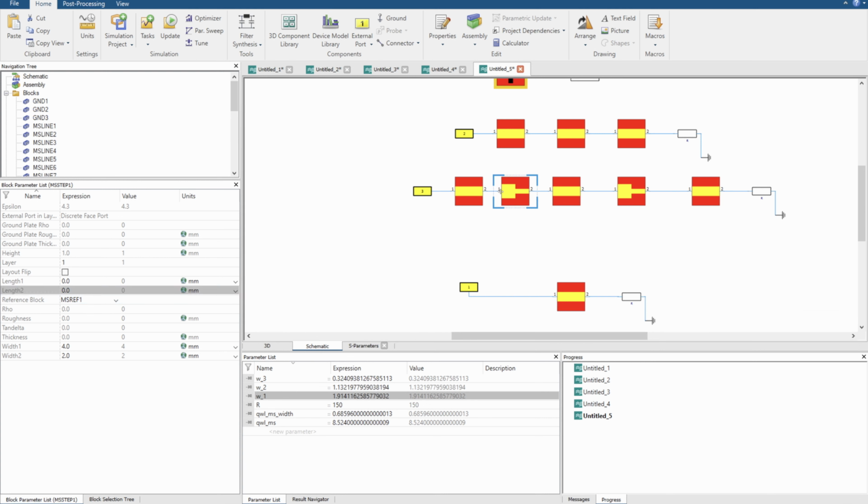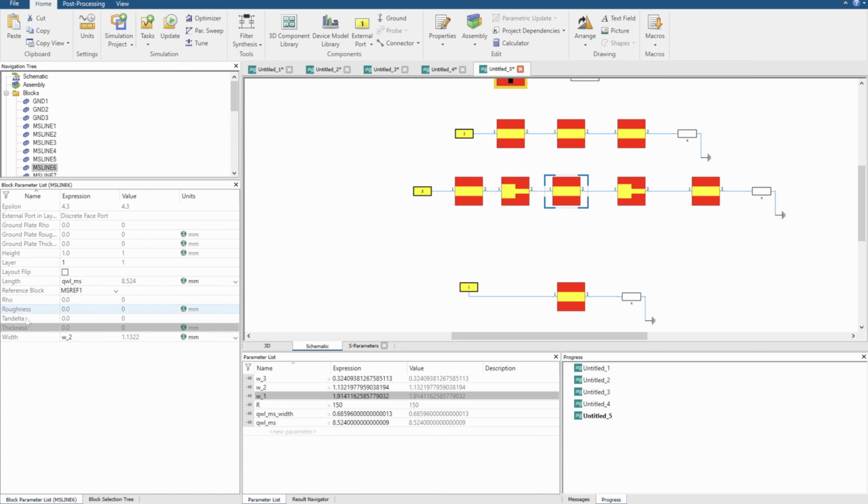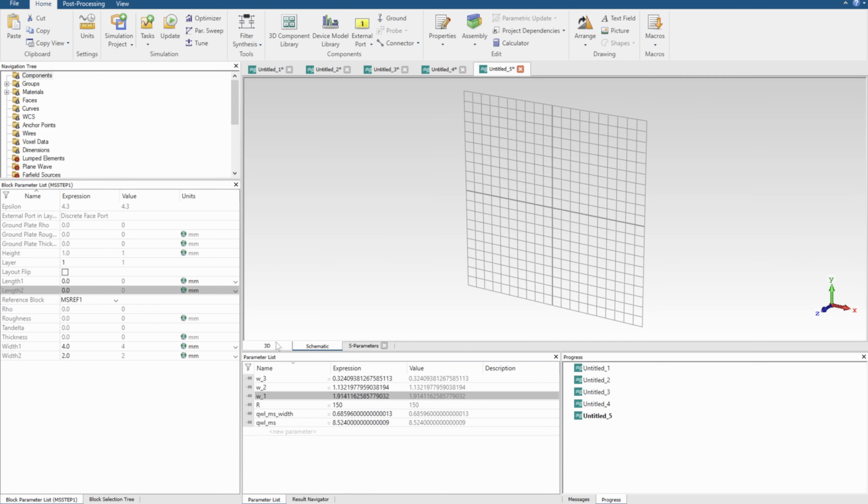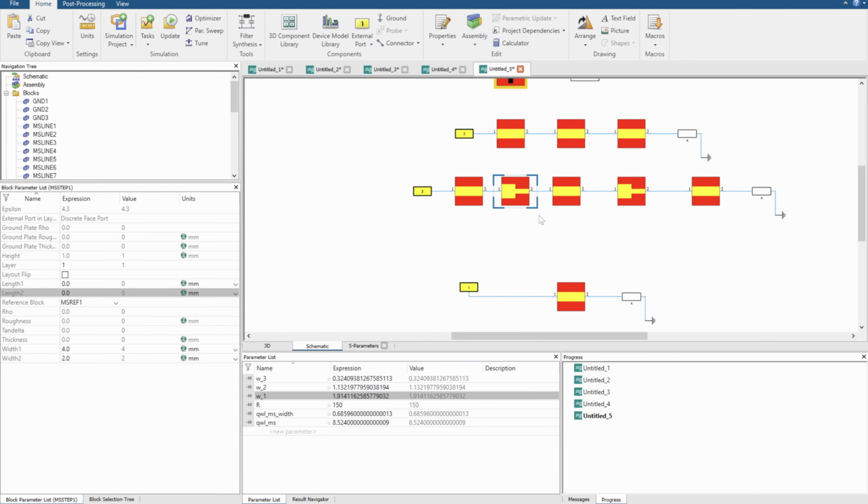However, we just want this block here to account for any type of reflections you see from a thin or even just sort of a step within the microstrip lines. Because this first element here, we've stated it's 1.19, and the second element is 1.13. So there is a significant difference. It's nearly half the size of it. So there's going to be some sort of reflections. And by not putting this discontinuity block in, we're not accounting for any of these reflections or loss in performance. So when we transfer it perfectly to the 3D environment, it might not perform as we expect.